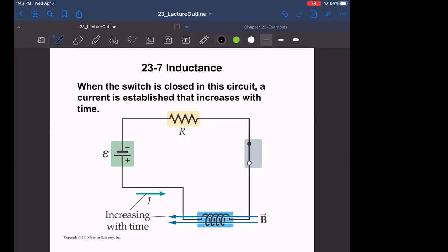Inside that is an inductor, because what it does is help get rid of any fast changing signals, any static, any noise. Any quickly changing frequencies don't have time to make it through the inductor, because if you make a quick change, the inductor says no and counteracts it. So only long changes get through, and you can actually filter out noise. You'll see those a lot. They filter out voltage spikes and stuff like that.